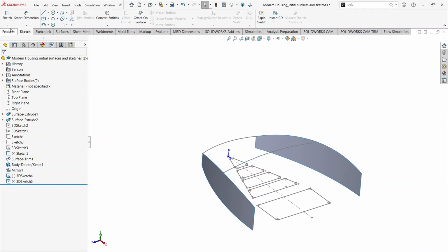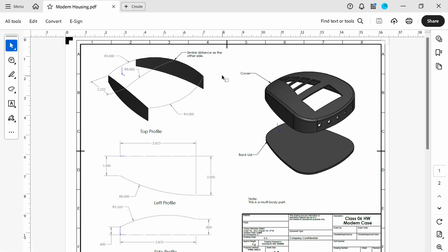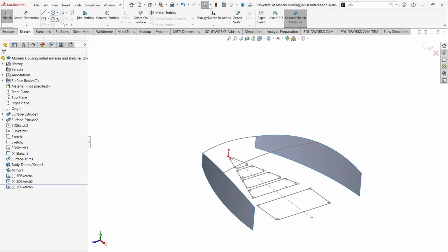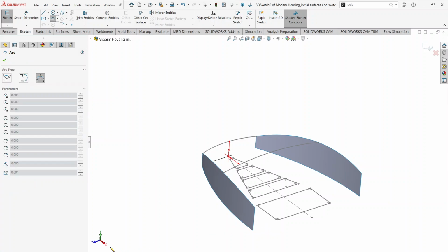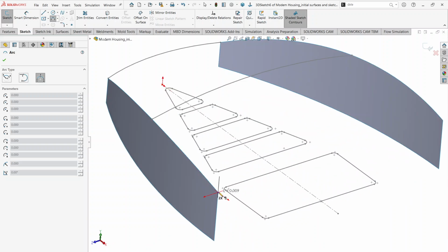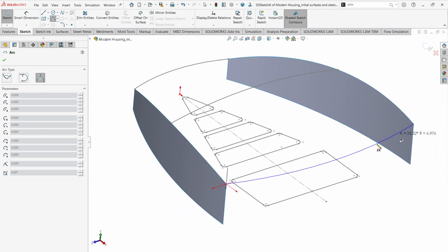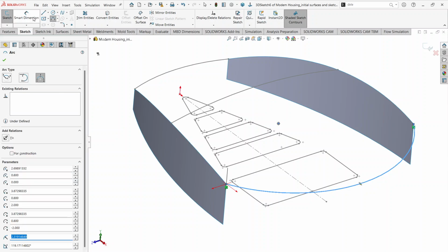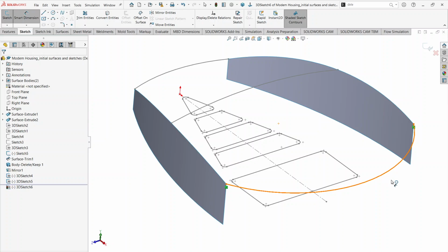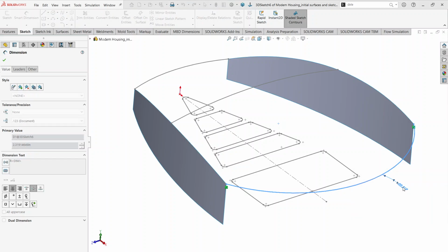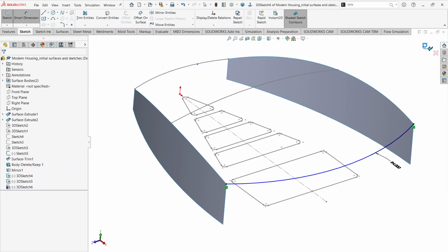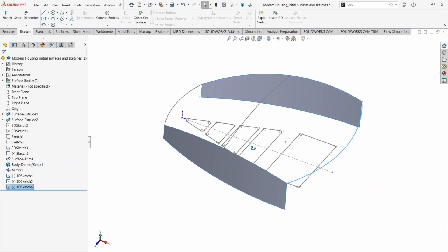Exit out of the sketch and start the third and final sketch, which, the last one, is again in a horizontal plane with a radius of 4. So pick this one, and the plane would be YZ or ZY, or I'm sorry, ZX. At a point here, second point here, leave it somewhere, smart tool, and at a radius of 4. Then this should be all the 3 sketches defined.